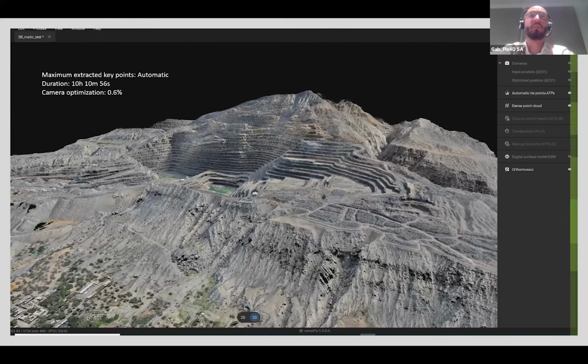So 4 expert drone pilots, 2 teams, 3 sub areas that the project has been divided into, and flying the drone at about 120 meters height with a very good overlap helped them to achieve basically a 3.3 centimeters accuracy level with the GSD that we've seen before, with the calibration and the first step of processing of 10 hours.